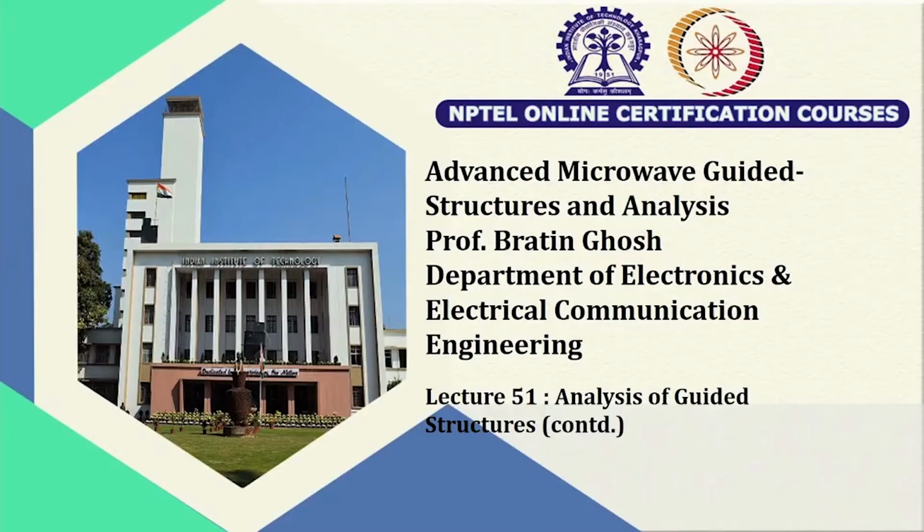Welcome to this session of the lecture on the dielectric slab guide, which is a continuation of the previous lecture. In the last lecture, we discussed the electric and magnetic fields inside the dielectric region for the TM even mode. We will continue from there and find the electric and magnetic fields in the air region for the TM even mode, for subsequent matching of the electric and magnetic fields across the dielectric-air interface in order to evaluate the propagation constant of the TM even mode.